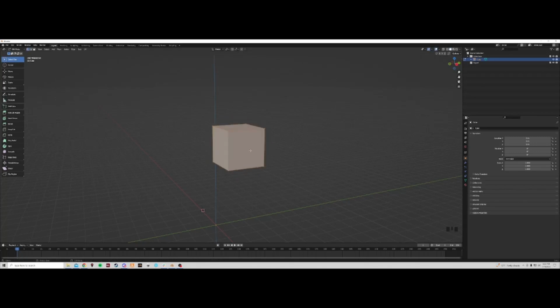Now, if I wanted to lock a specific axis, same scenario. If I want to rotate on Y, I would press Y. Now it's rotating on Y, X, Z. If I want to exclude one, same thing, Shift Z, Shift Y, Shift X. The only thing is, this doesn't really rotate well. You can't really exclude only a single axis. It will generally only lock to the single axis.